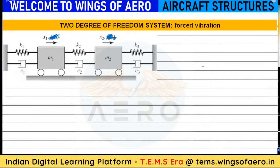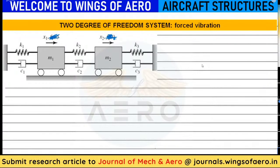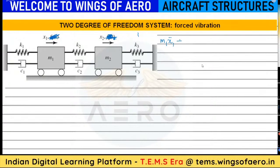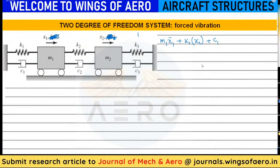All right, so tell me the equation. Can anyone unmute and tell me the equation? M1, we have two displacements here, x1 and x2. So M1 x1 double dot plus the stiffness of the spring K1 into x1, plus C1 into x1 dot.